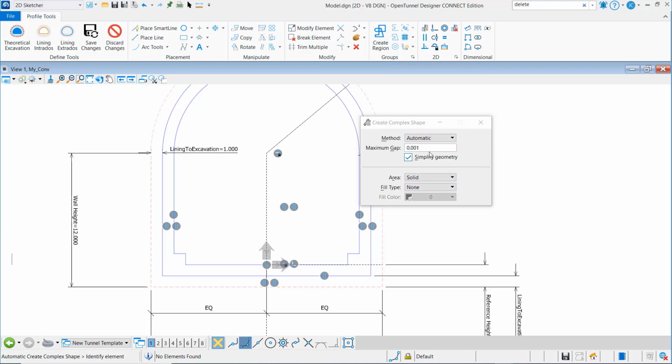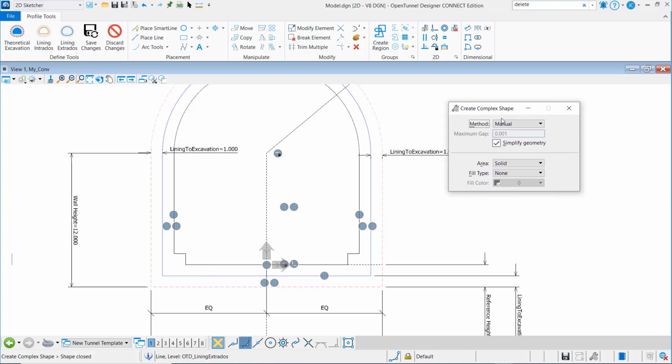So be careful not to use an existing constraint element, otherwise it will remove the constraint. That's why I choose manually to point to the element, to be sure, mainly at the horizontal part, to choose the last element I have created and not the reference dotted line. Here I have created this complex shape. Now I can put constraints in it.